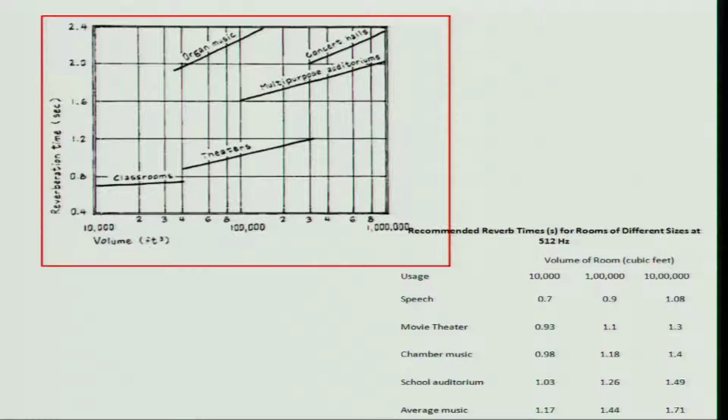But the calculation of the reverberation time will be based on Sabine's formula, which we have discussed so far. So this is what I wanted to discuss in this particular lecture, and in the next class we will do an extension of this, and we will introduce anechoic chambers, noise reduction coefficients, sound transmission coefficients, some of these terminologies. That's what we are going to cover in the next couple of lectures.